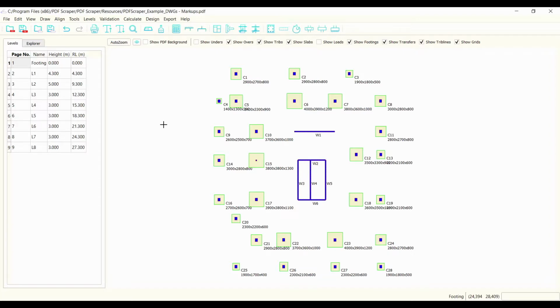And obviously when you think about it, particularly the depth of the pad footing is highly dependent on the size of the column that sits on the pad. So actually I've done this probably in the wrong order. I've optimized the pads before the columns. In reality, you'd size your columns and then you'd use that column size to appropriately size the pad so that the punching shear and shear and bending checks consider the appropriate sized column.